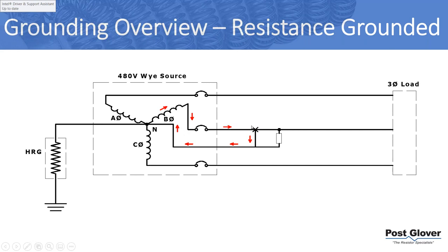If you have a short through here, or maybe even a ground fault somewhere else, you are creating yourself an additional path that can bypass it, and therefore you may have a fault. You may have a dangerous situation you don't even know about. So it's an NEC requirement to not have this.